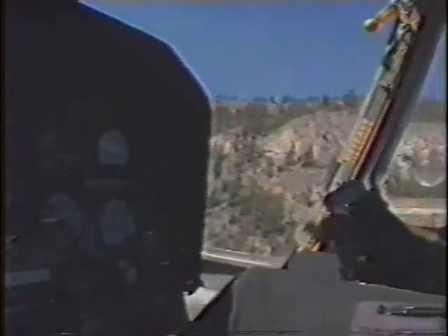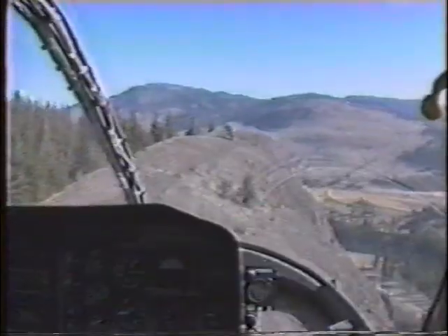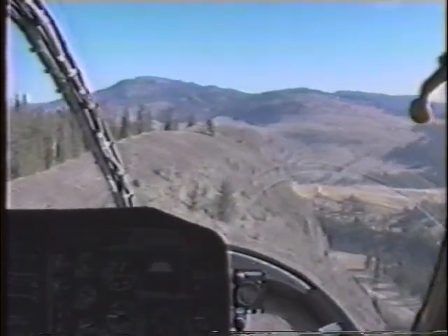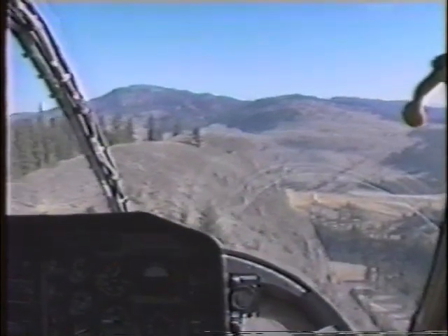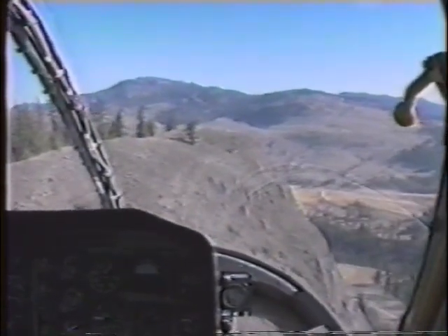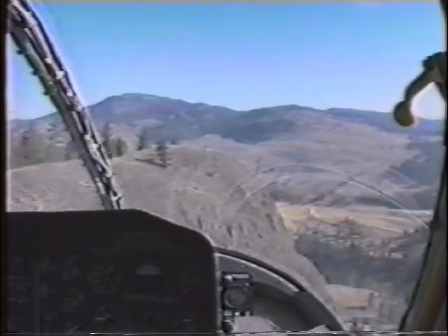Once you've got a good feel for the situation, you begin your approaches to overshoot. These passes will give you the chance to confirm the winds and look at the LZ, the approach path, and departure path. They'll be much like your final approach, except you won't have to worry about losing translational lift.